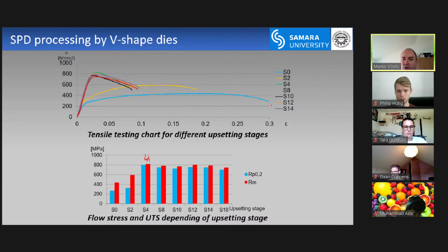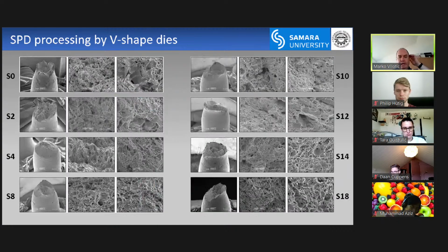Also here. And you can notice one thing here in terms of tensile stress. So this is tensile testing. The elongation here, the strain is 0.3, but elongation here drops to, let's say, 0.18, and in this case 0.1. So a 3 times reduction of elongation. But we will see later, it's still okay.